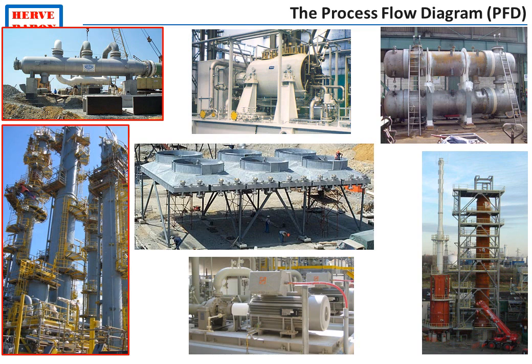Equipment performing a hydraulic function such as compressors, pumps, or a heat exchange function such as heaters or heat exchangers are simply specified by process, but they are not designed, they are not sized. Their sizing, the sizing of rotating equipment and heat exchange equipment, is done by the equipment vendors.